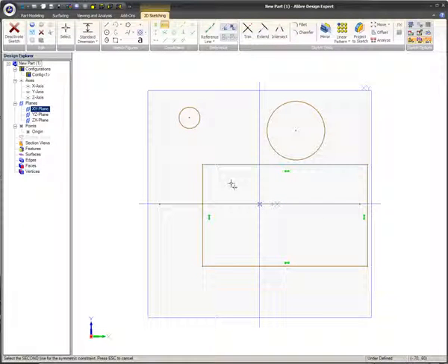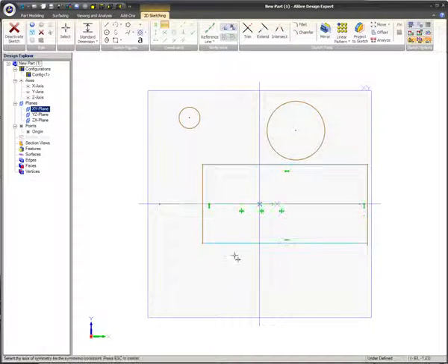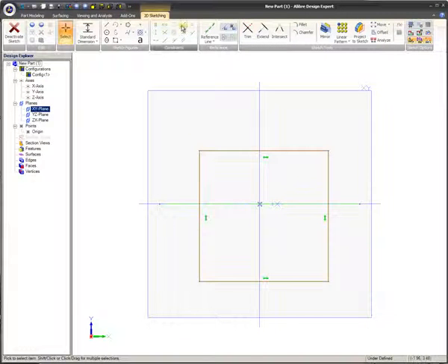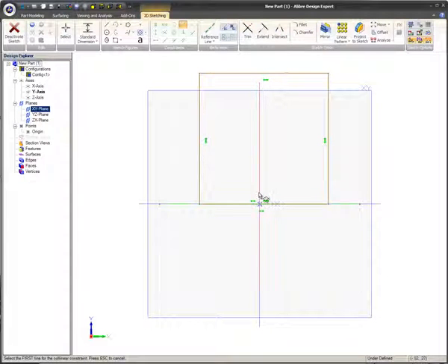The line selected immediately after selecting the axes determines the length, angle, and distance from the axes for the second line selected, essentially creating a mirror of its partner that was selected first. This works with lines, circles, ellipses, and arcs. Here you can see the collinear constraint lining up the edges of this rectangle with the X and Y axes.